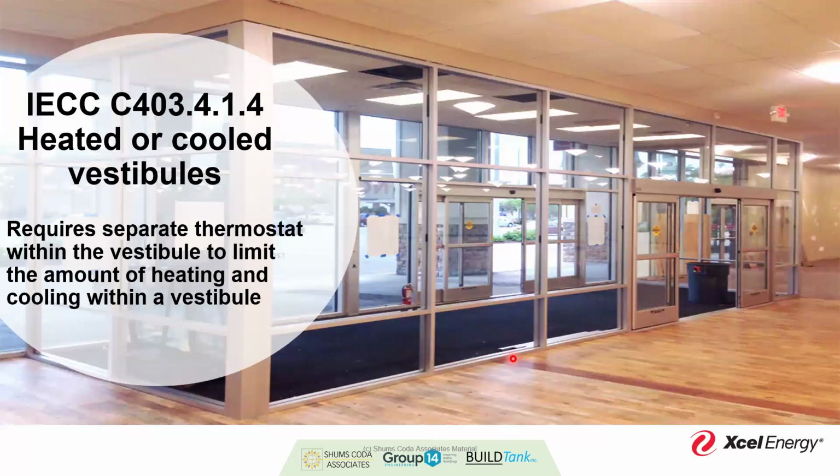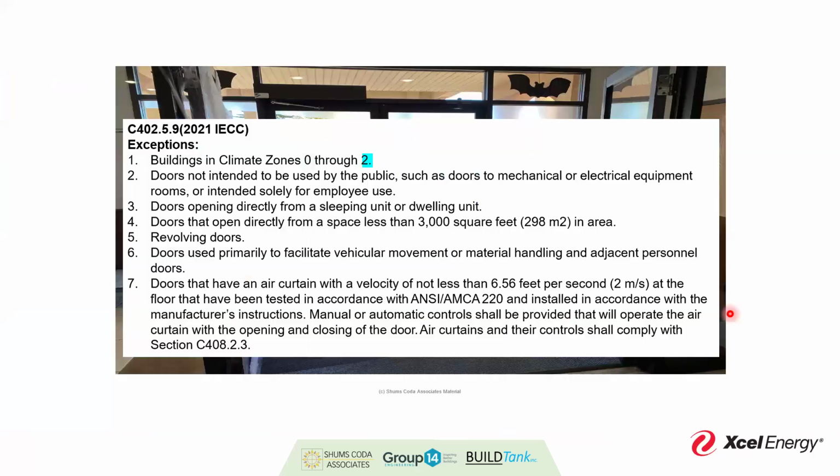Then we'd be subject to freeze, thaw, and lose that sprinkler head or cause multiple issues with it. Maybe it doesn't respond when you need it to, all of that good stuff, right? So that was the intention. And then it kind of got crowbarred in to also allow the cooling element as well. Wasn't really the intention to be tied to it, but now regardless, when you cool or when you heat, you have certain limitations of what you're allowed to do in terms of your set points for those areas, and you do need to have it independently controlled.